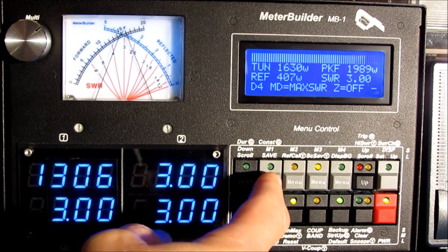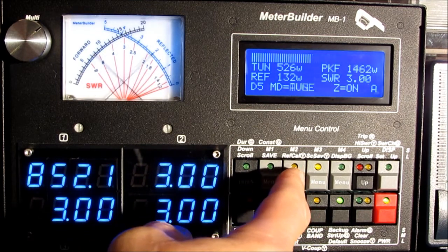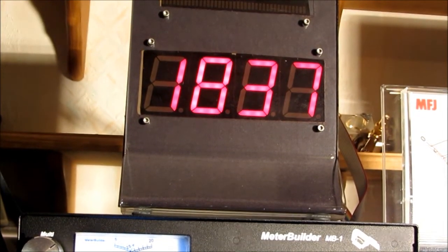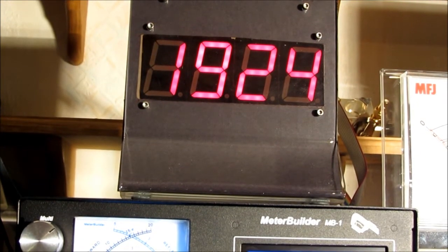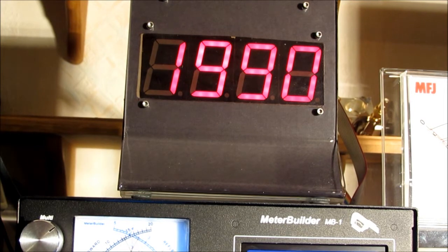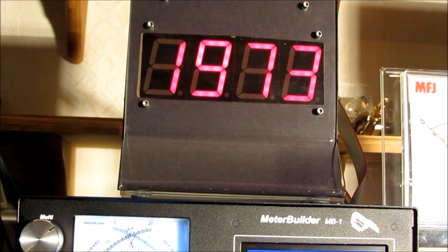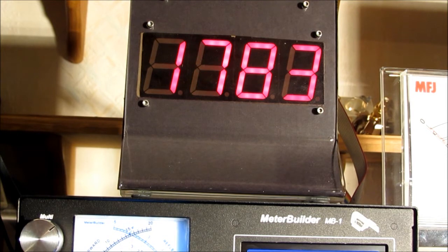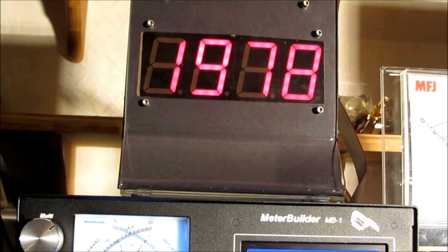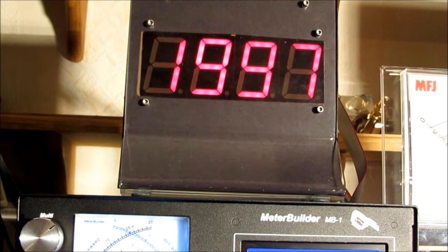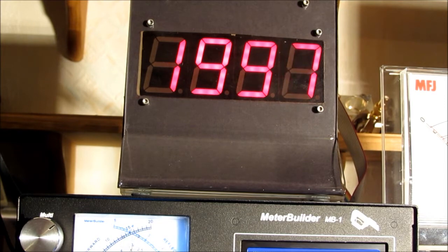a 5th meter on the top, the external display, that I'm going to set to peak forward. Okay, so you can see right now we're approaching the 2000 watt full scale value for some of the peak measurements. So you have the ability to control up to 2 external 7-segment displays. In this particular case, we have the meter configured for 1 7-segment external display and 1 bar graph. So in this case, you are limited to 1 7-segment external display. But in this case, we have 5 separate measurements being displayed simultaneously.